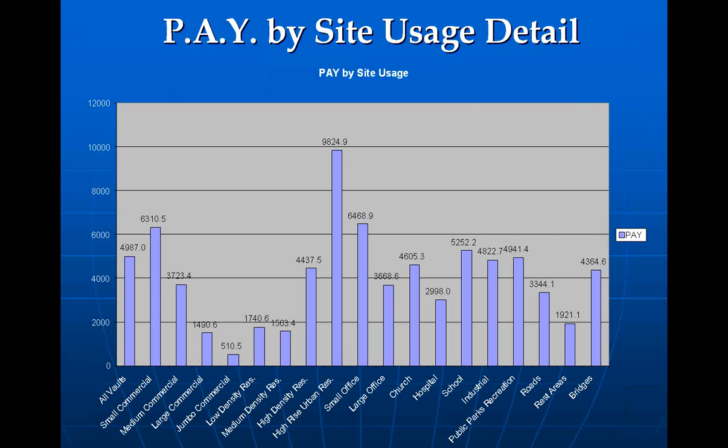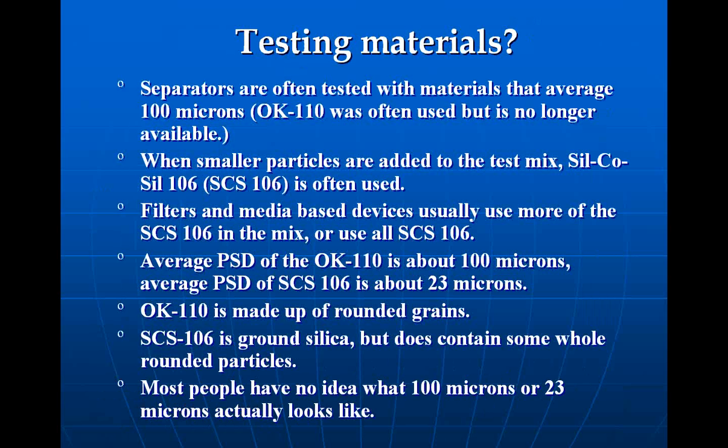So this variability of just the gross amount of material is reflected in what you see in the BMPs. Now, separators, there are two types of BMPs. I wrote about this in 2004. I did not call them separators. I called them gross pollutant or hydrodynamic devices that depend on settling. And then I talked about devices that could catch smaller particles like infiltration practices, large wet ponds, constructed wetlands, things like that with a very low energy gradient through them.